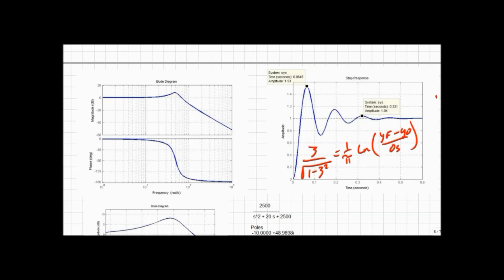In this case, yf equals 1, y0 equals 0, our overshoot equals 0.53. If I assume that the square root of 1 minus zeta squared is pretty close to 1, then I can erase this and say zeta is equal to that, and I come up with zeta equal 0.202. So there, that's that method again applied to the step response.